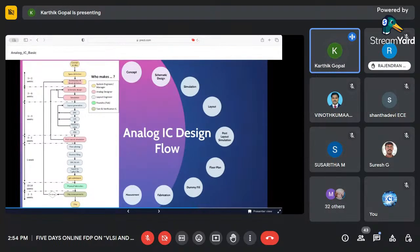So then everything is done. So this dummy DRC, dummy filling, and again they'll do the DRC for the whole chip. And this exports to a .gds file. So what they do is they export this GDS file to the manufacturer. So till this, the layout engineer will do. So all has been done.